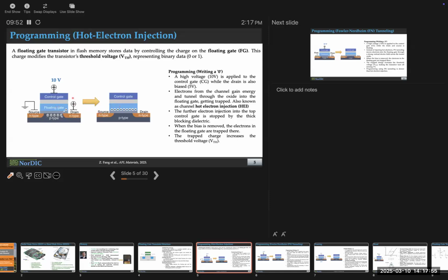So there you go. Once you do that, you have a layer of electrons that is a fixed charge. Compare that to negative polarization in a ferroelectric. There you go. Same concept. Next time, when you turn on the transistor and there is a current flow, you'll see a difference because the threshold voltage will shift. Are we all good?